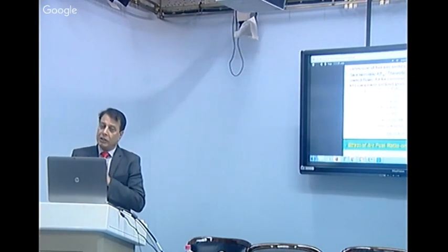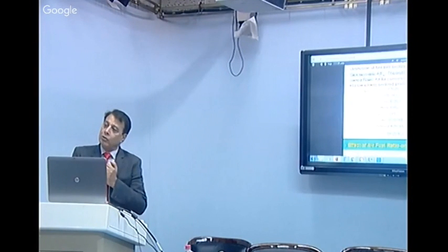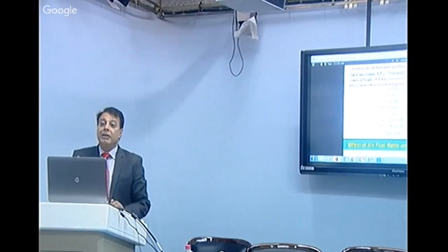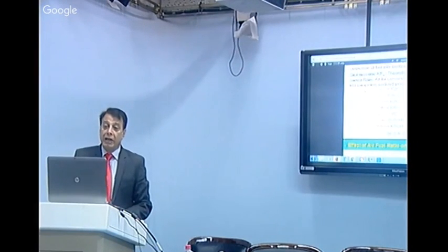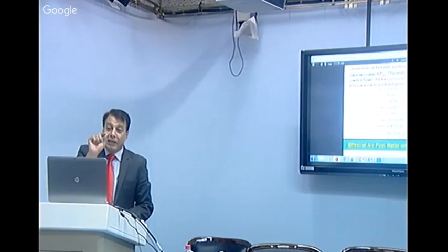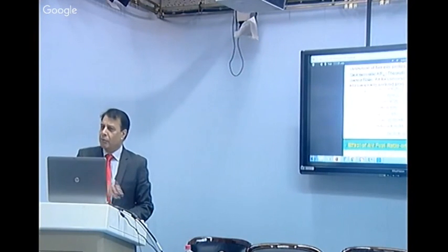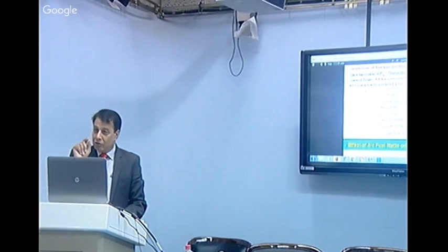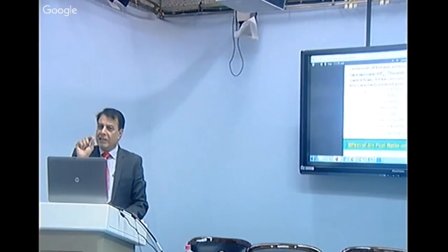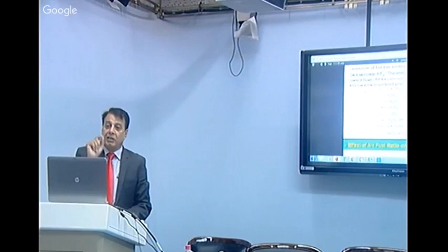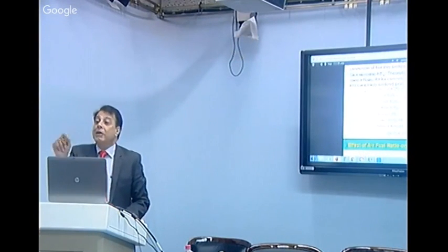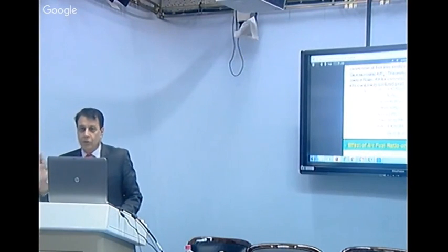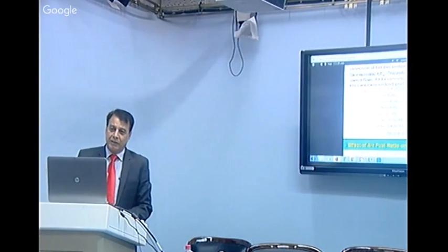And even now you can think, what type of paper should I use for the air cleaner? Are you getting me? There are different types of paper, non-woven type, and what should be the pore size of that paper? Even that is very important. Like I told you, for the sieve, the paper also has pores, and if the pore size is supposed to be 20 micron, it means dust of size less than 20 micron will be carried with the air. So that is also a very important aspect.